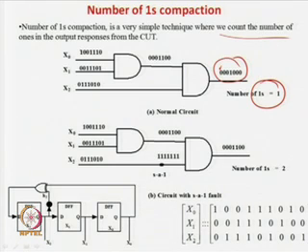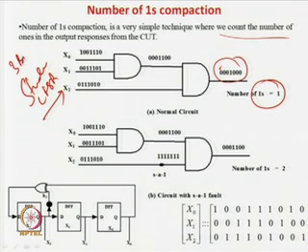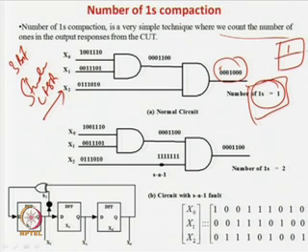The ROM will say that if you are using the standard LFSR, the 3-bit LFSR, and we give this as an input as in the last example, the circuit under normal case will have only a single one. So, the ROM will now store only one for this whole set of inputs. But if you are using flat storage, you have to store this whole 1 0 0 1 and so forth.